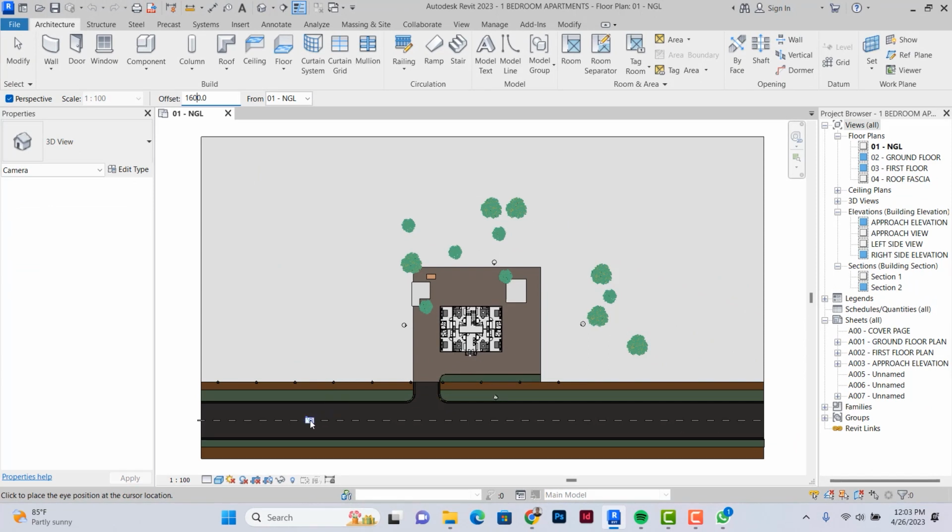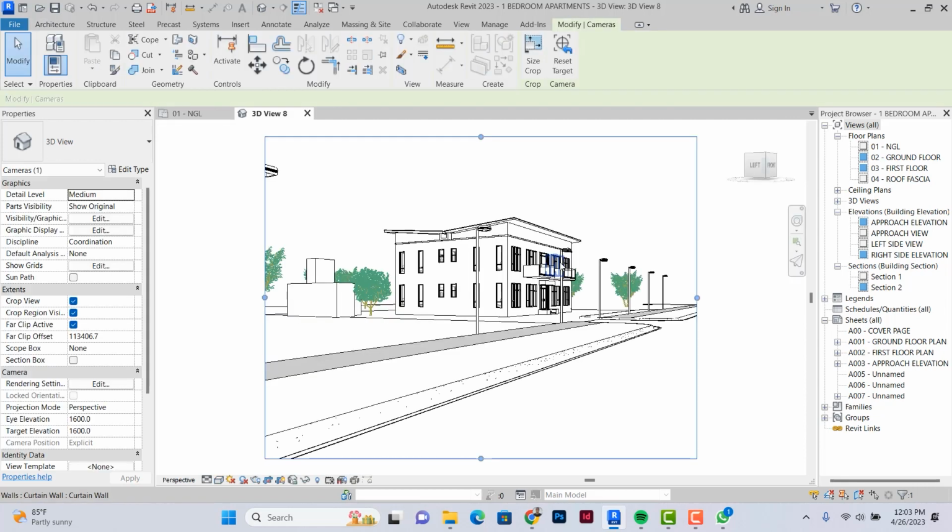So you position the camera. Once you position the camera, you notice straight lines radiating from the camera. Now the two extreme lines are showing you the view extent of the camera, while the middle line, which moves with your cursor, shows you the target of the camera. Position the target just behind the subject, which is the building in this case. The camera automatically creates a view.